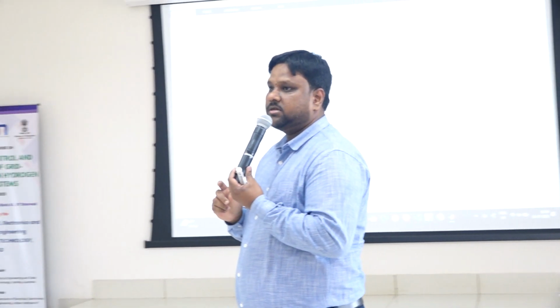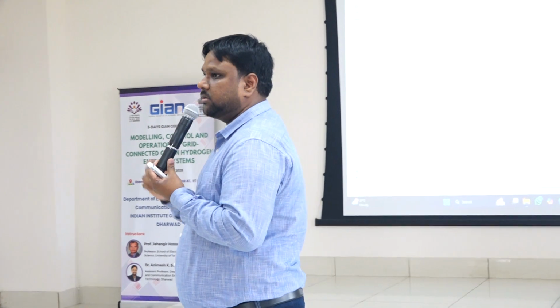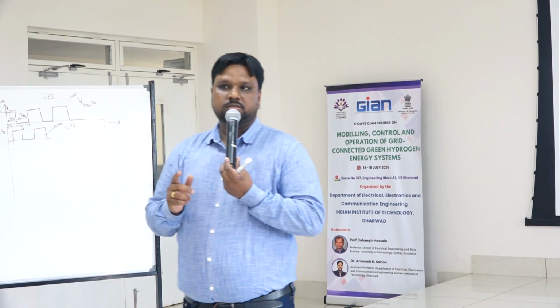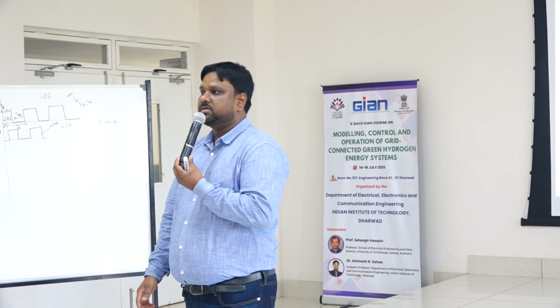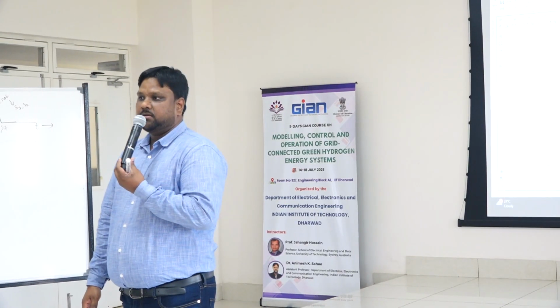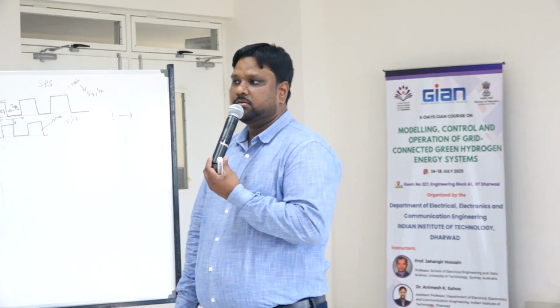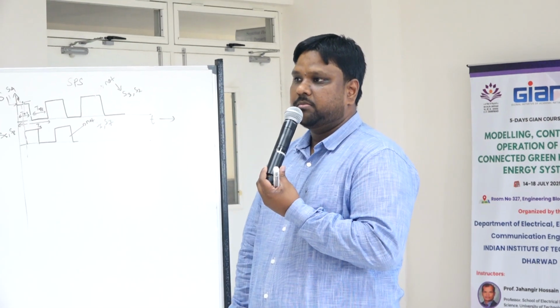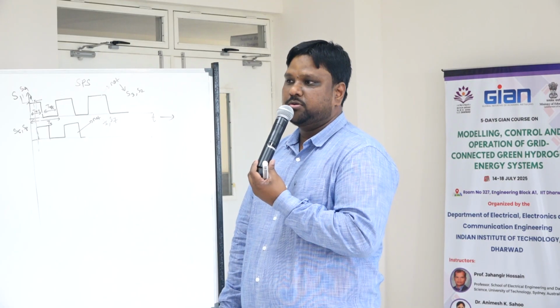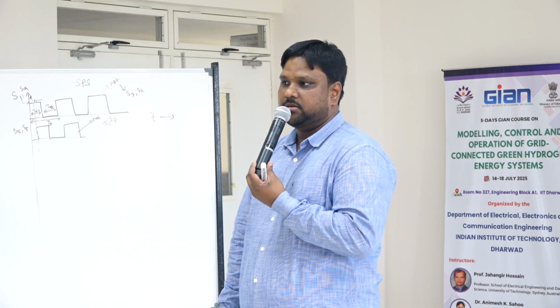So now we'll enter the sliding surface equation, which is the heart of sliding mode control. That equation involves the measurement of a voltage error. So how will you measure the error? Reference value minus measured value, and the reference value we want at the output is 262, right?